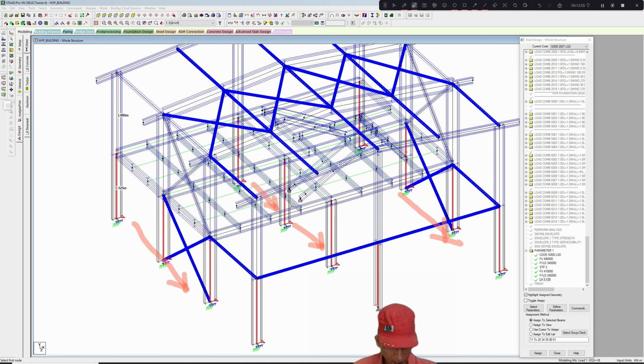So we have LY as 3.125 meters. About YY direction, they are all released, they are not fixed. So pinned at bottom, pinned at top, these members are having cleat connections. So pinned at top, so effective length will be 3.125 meter.